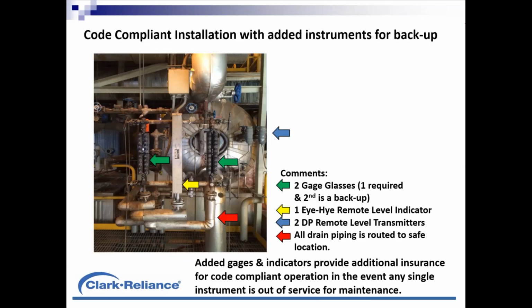with 2 transmitters. I'd also like to highlight, you can see the drain piping coming off of these gauges, coming off of that conductivity probe device. These are in walkways where an operator might walk by. They've got all that low end piping very nicely insulated so that no one suffers a burn risk down near knee height. And some of the areas on platforms near this equipment can get very tight.